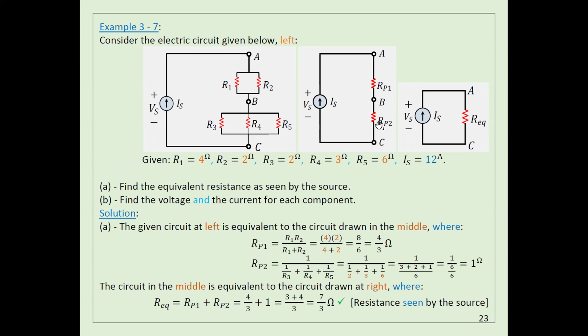Okay, you have the formula. I don't need to repeat it again. You have the formula that can help you to calculate the equivalent resistance for these two, and also the equivalent resistance for this one. Now this resistance and this resistance are in series, so the voltage here is going to split across them. It's the same current here, it's the same current here. So I can just add these two together to get the equivalent one.